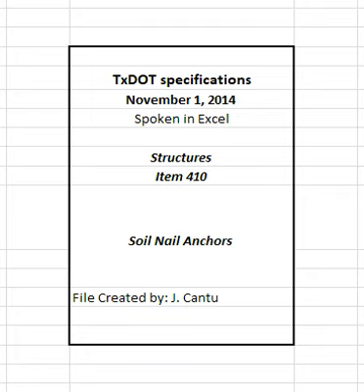Details of pneumatically placed concrete equipment and application, including mix process, shooting methods, and means for determining the thickness of the concrete applied. A nozzleman who is certified as an American Concrete Institute (ACI) shotcrete nozzleman. Plan and methods for nail testing, both the verification tests and proof tests, with calibration certificates dated within 5 months of the submittal date, and other information shown on the plans or requested by the engineer.